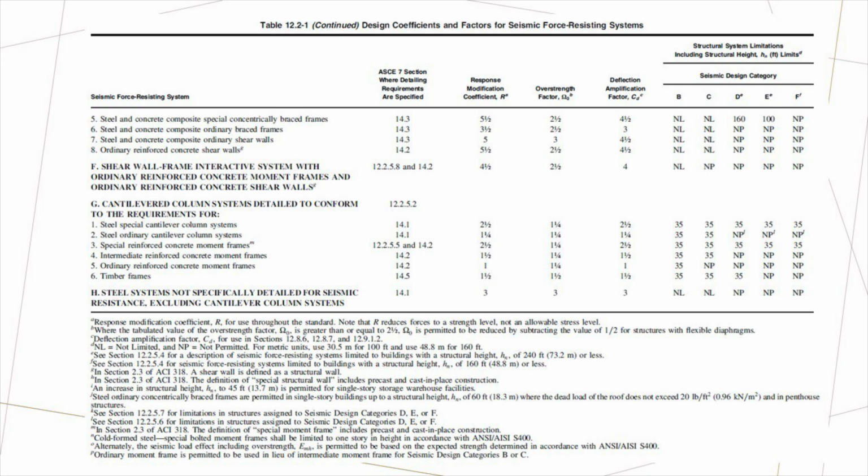Because seismic design assumes this controlled inelastic response, we use capacity based design for collectors, braces, and anchorage so these elements remain stronger than the intended ductile components. Finally, the seismic forces are distributed vertically through the structure based on mass and height, ensuring that each level is designed to resist its appropriate share of the total lateral load.